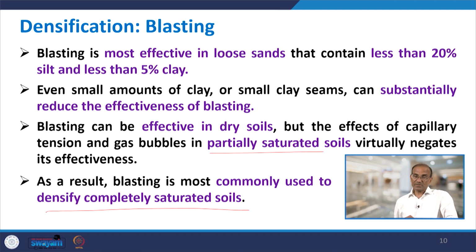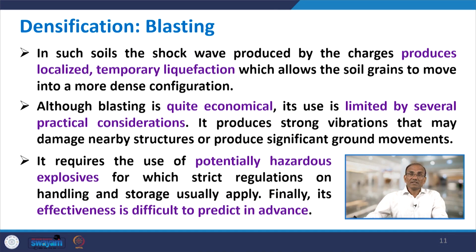So, partially saturated soils have problems for this blasting technique, the reason being that there could be effects of capillary tension and gas bubbles, and they can reduce or even eliminate the effectiveness of blasting. In saturated soil, the shock wave produced by the charges produces localized temporary liquefaction, which allows the soil grains to move into a more dense configuration.